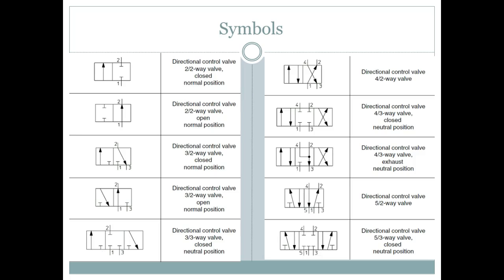You understand? But on pneumatics, we use air or gas, and of course air is the predominant gas. I've never seen a pneumatic system that doesn't use it, but I know where it might be used. In an extremely cold environment, a lot of times they'll use a pressurized fixed gas, and then you have to have a closed system. If I'm using nitrogen, I don't vent that back in the air. I'd have to return it to the tank, right? Does that make sense? But in this class, all we're going to talk about is air as a gas, which is probably used in 99% of pneumatic systems.